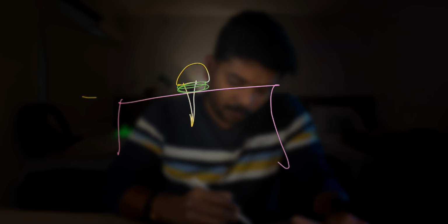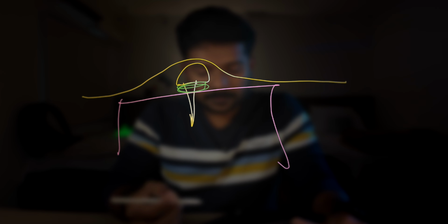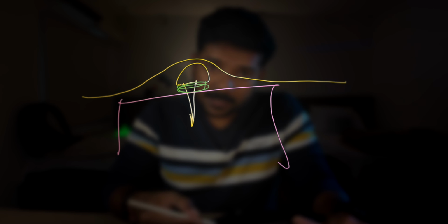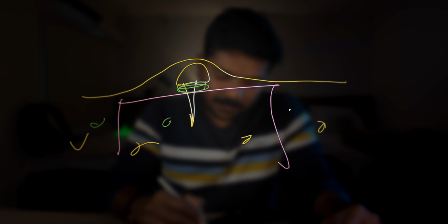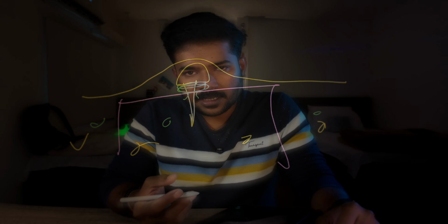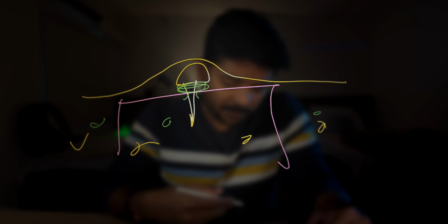Drainage and waterproofing, that is also one factor. In this example where we discussed stainless steel screws on aluminum, we can have a waterproofing membrane on top of it covering the whole assembly. What this waterproofing membrane does is prevent water from entering the system. If there is no water, if there is no moisture, the battery is broken and bimetallic corrosion is prevented. Yet there are possibilities of condensation since there is air inside, this air might condense onto these joints and seep in, causing corrosion, and those must be thought of during the design process and tried to be prevented.